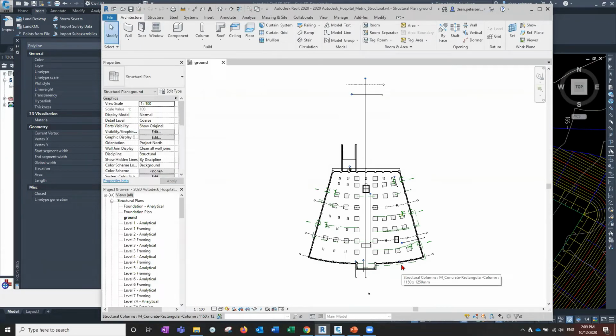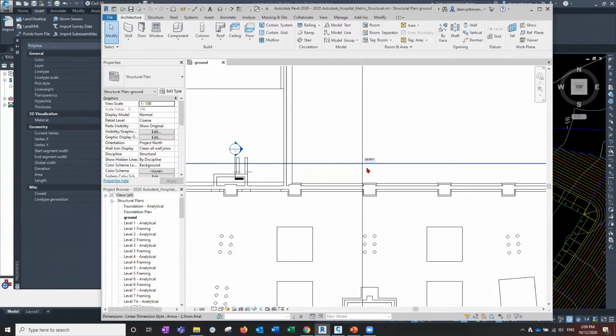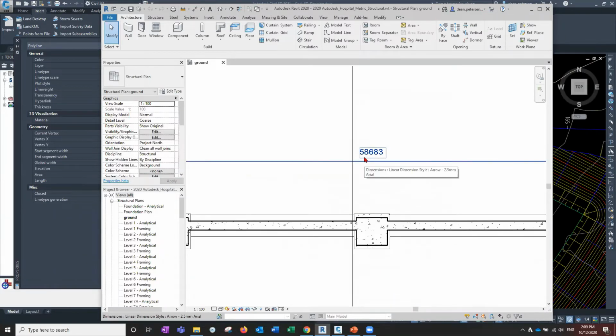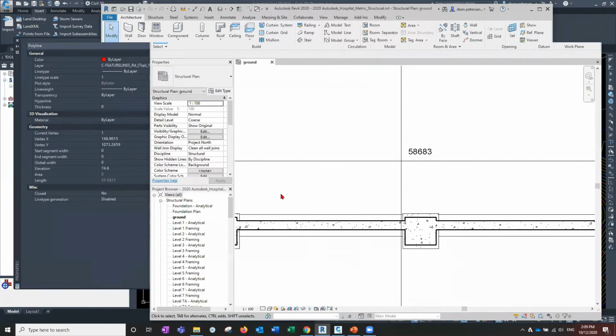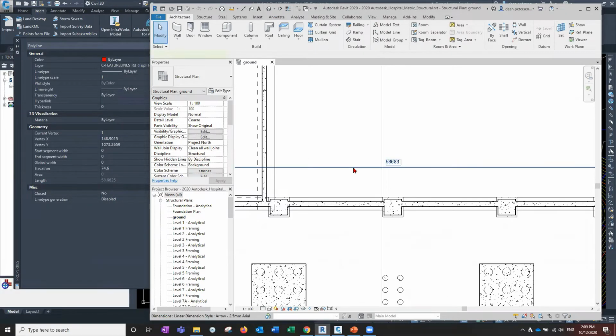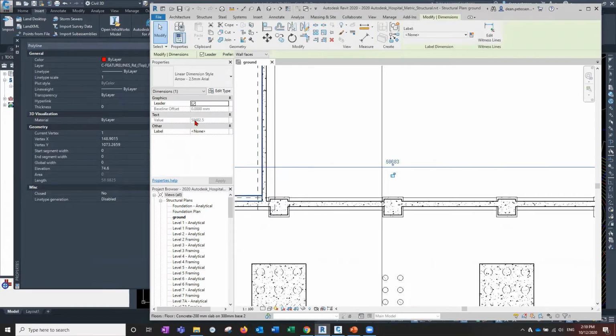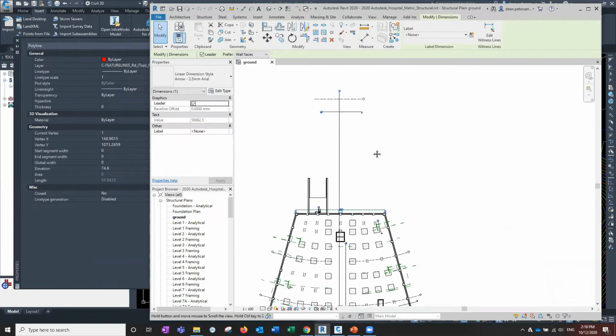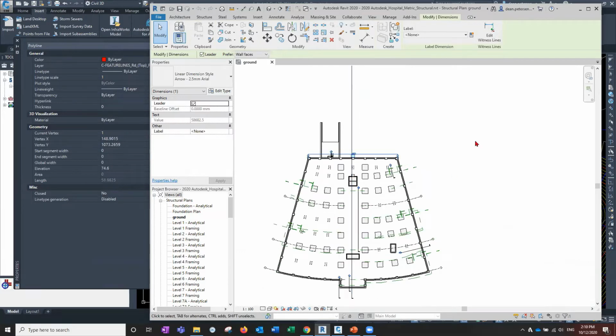Here we go. So here we've got a base plan for the Revit model. This is actually at ground level. This has been produced, and here is the same dimension that we had back in Civil 3D. Though this, I think you'll find, is rounded, truncated, which it is. If I actually pick that, we should get the actual value. There we go, it's millimeters, 0.25. So they need to be exactly the same. Otherwise, the coordinate system is not placed correctly. It'll be, you know, tens of meters out because the origin is so far away.